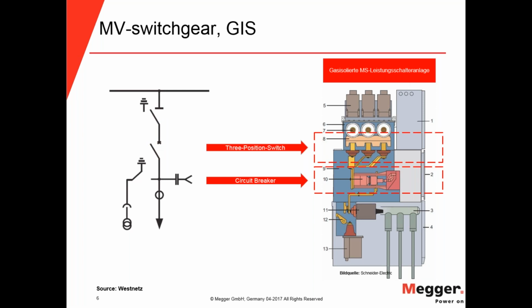And down here you have your voltage transformer, and this earthing switch is only to ground the voltage transformer actually. So you cannot ground the circuit breaker with this switch, because this switch goes either to ground or to this part.